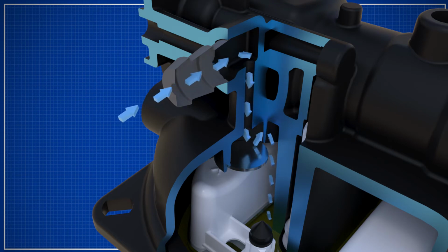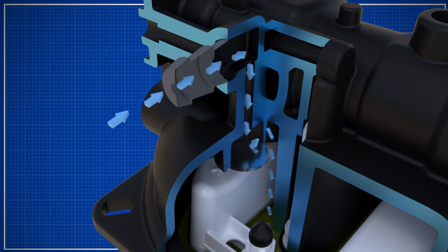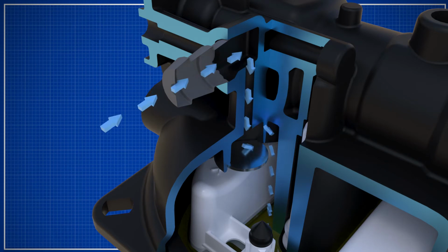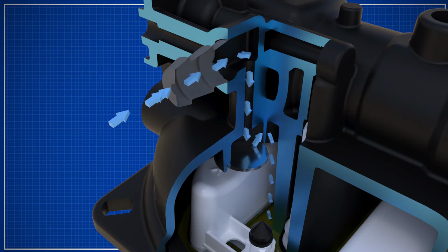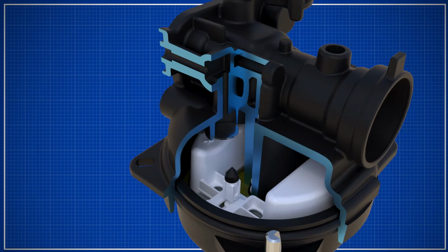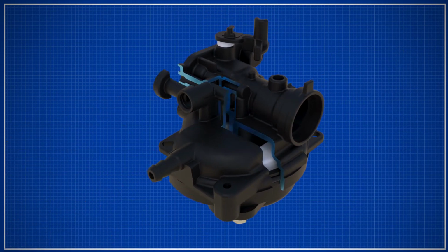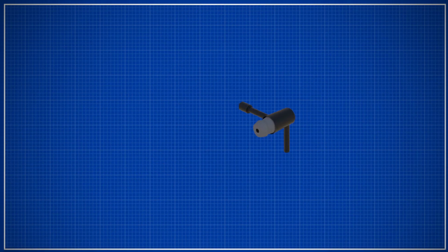High and low-speed fuel circuits use air bleeds. Air bleeds are one more type of restriction, like a jet, but they only meter air. Air bleeds are calibrated to let air go into the fuel circuits to start the atomization process before the fuel goes out of the fuel circuits. This process makes the fuel supply consistent and engine performance better.